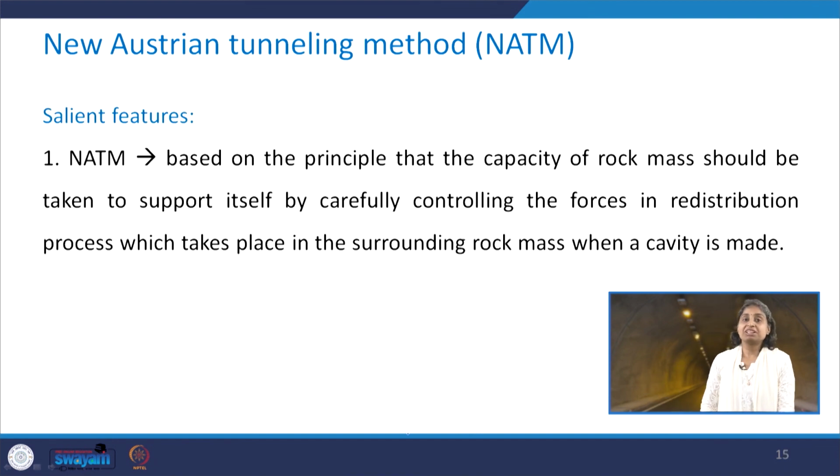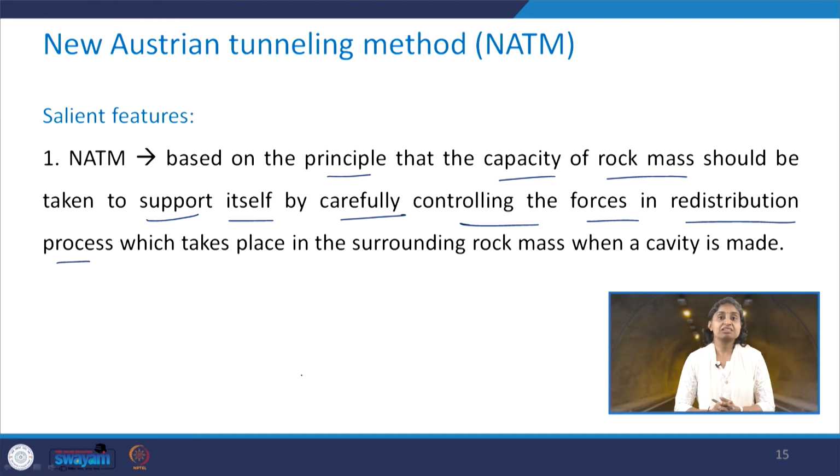Coming to some of the salient features related to NATM. This is based upon the principle that the capacity of rock mass should be taken to support itself by carefully controlling the forces in redistribution process which takes place in the surrounding rock mass when the cavity is made.